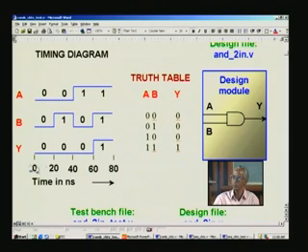Now you also see one more axis here, the time axis, because once you say timing diagram you need to refer to a time base. Let us say we start arbitrarily at one point, which we refer to as the 0 point. So time starts here. It always goes forward fundamentally, unless you take the reference somewhere at a midpoint. So to start with, we will simplify by saying that this is going to start at 0, and let us say the time axis is marked in nanoseconds. So you see that at 20 nanoseconds we make a second transition here.